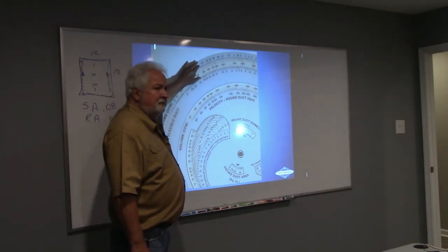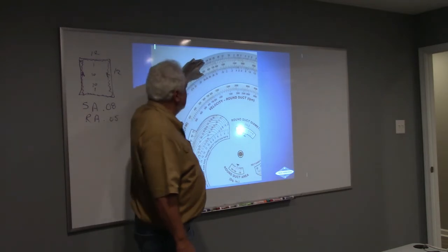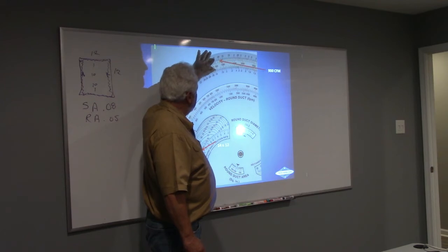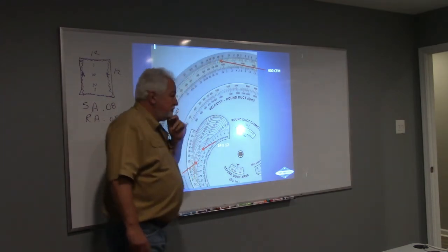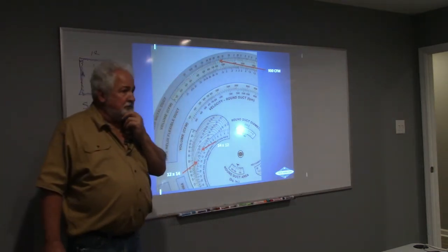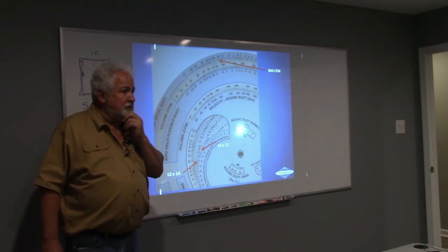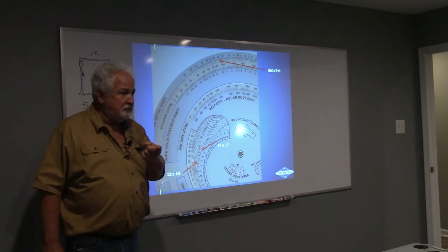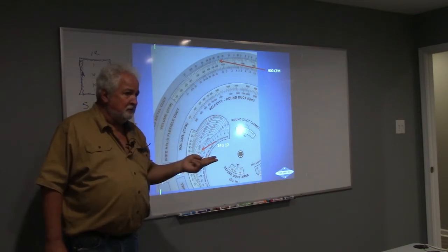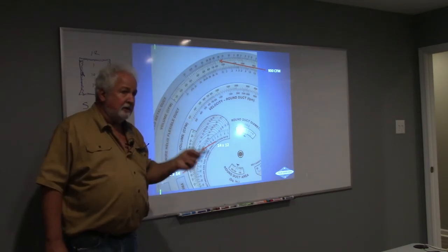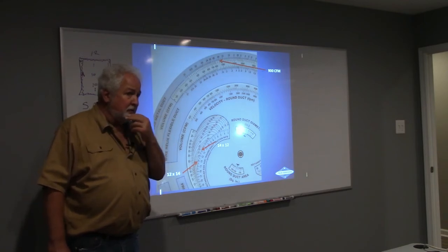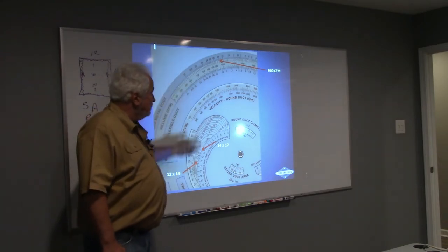Is that a supply plenum? Yes. Supply. So I'm going to go to what? 0.08, right? 14, 12, and 0.08. How much air can I move through there? 900. Good. So I was right. It was 900, yes? So we got problems with the return air grills and the supply air trunk. That's where your biggest problem was on that one we made the loop on, okay? Supply air trunk. So good, we're there.